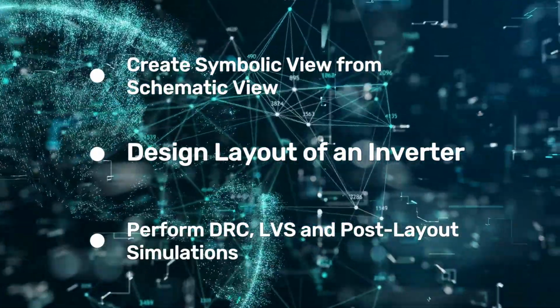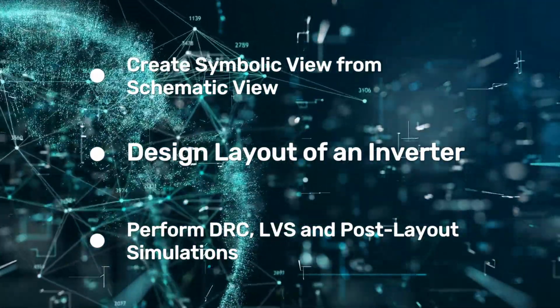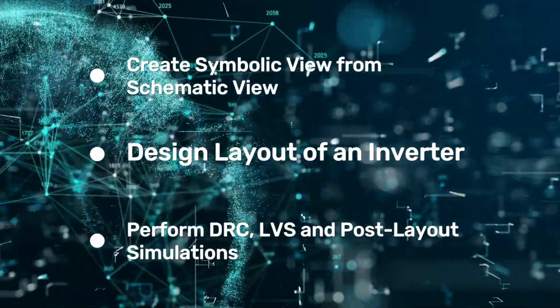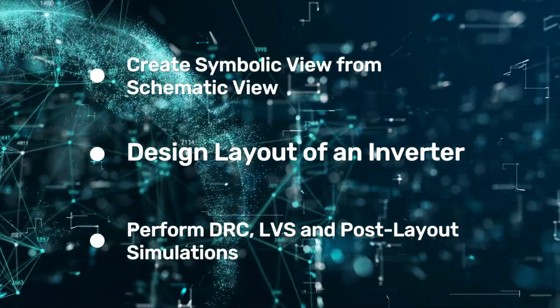So in this part we will be performing DRC check, design rule check, layout versus schematic check, and also we will extract parasitic resistance and capacitance from the layout and perform transient simulation of this extracted view.